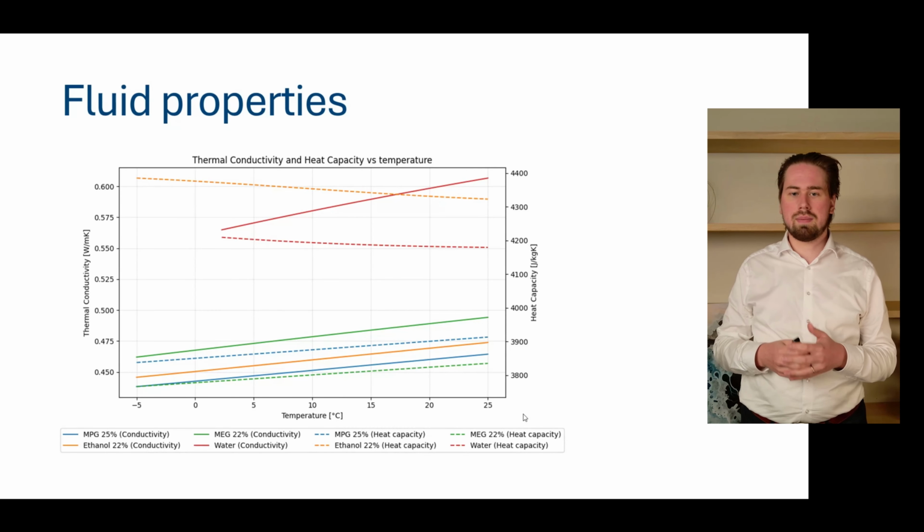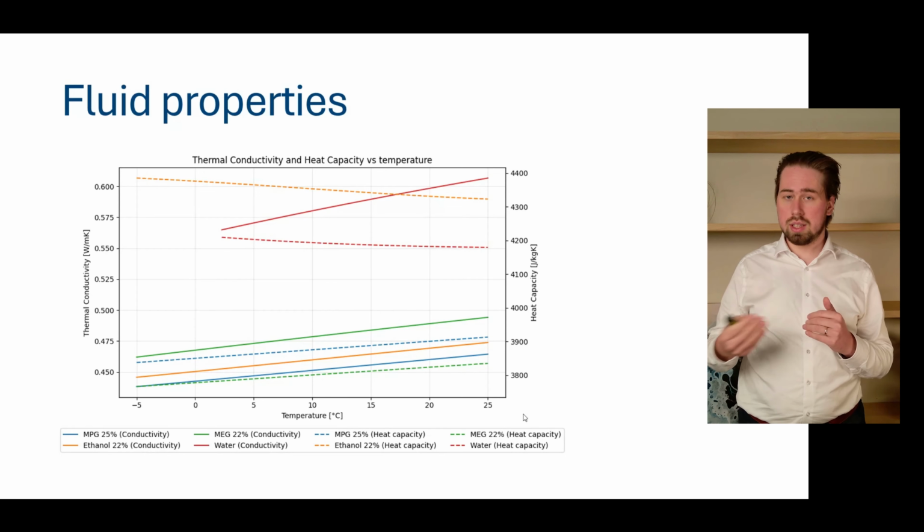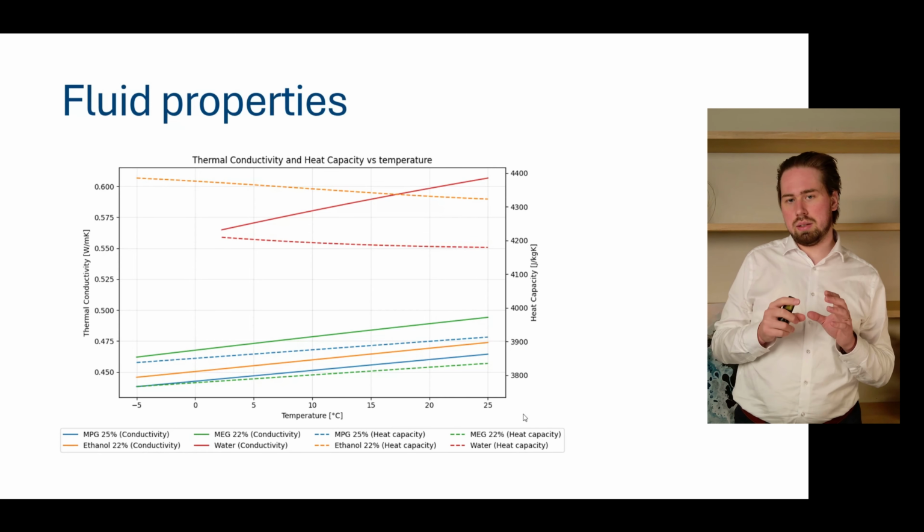Now, why do we care about these fluid properties? Before we talk about that, just the same story here for the conductivity and the heat capacity. Here the story is a little bit different, because if you look at the solid lines for the conductivity, they increase with temperature, so the heat transfer becomes better with higher temperatures. Also here water is quite significantly above all the other lines. And when we talk about heat capacity, all heat capacities also increase when our temperatures increase, except for water and ethanol mixtures, where there is a slight decrease.